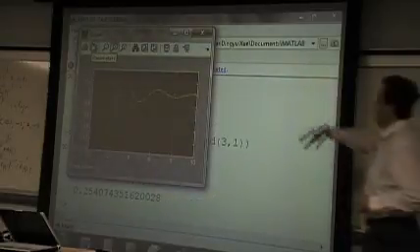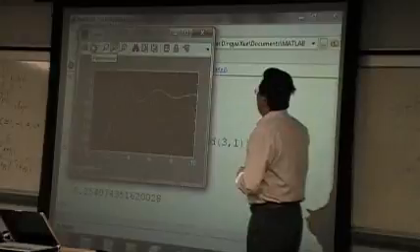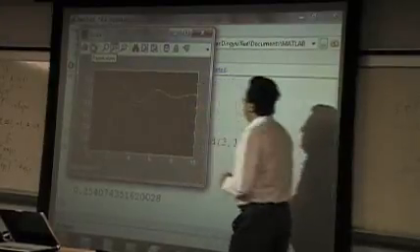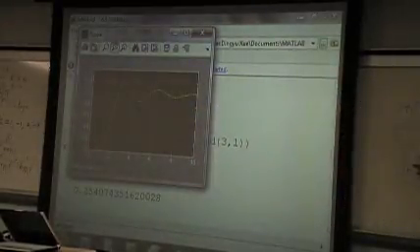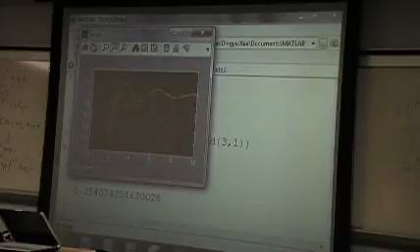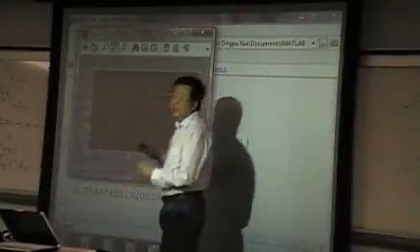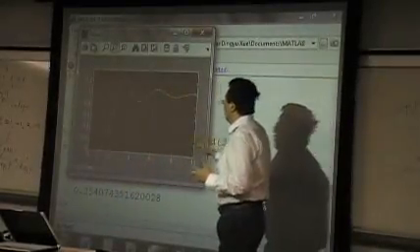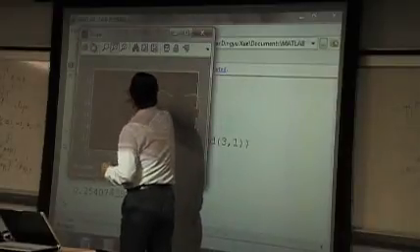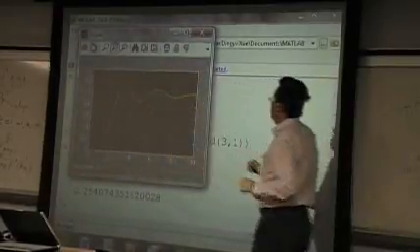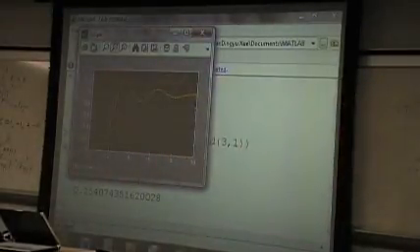There's oscillation there, you know. So why are there oscillations? Because it treats the error signal at any time equally. So it doesn't mind whether the error here is large or here is large. It only needs to have the integral small. That's the target of the ISE criterion.